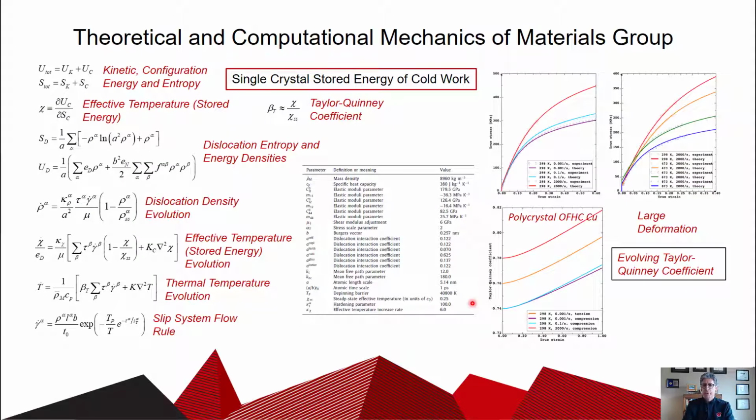And then finally, we care about how the thermodynamics of materials transform. So for example, if you're chewing gum in your mouth, every time you bite down on that piece of gum, you're going to increase the temperature a little bit. Well, metallic materials are very much the same way. If you deform them, then the energy that goes in deforming them is going to be dissipated as heat, so they'll heat up a bit. If you deform them a lot and very rapidly, they'll heat up a great deal. And so that's what the term stored energy of cold work is meant to portray.